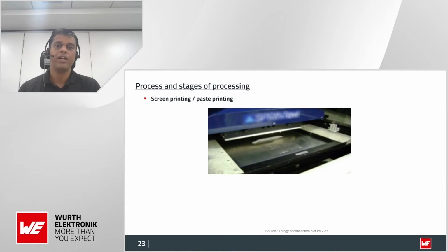The solder paste which we use on the surface of the PCB is a combination of flux and metal. The metal content is 50% or more. We need to apply the solder paste twice so that there will not be any air bubbles or gaps in the PTH, the plated through hole. And one more thing: when applying solder paste on the PCB, make sure the angle of application is more or less 45 degrees, so that it fills the PTH properly.